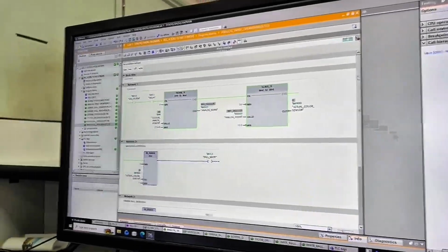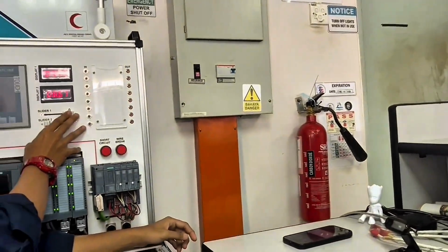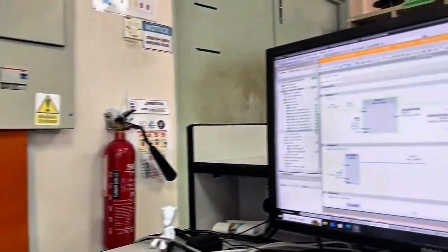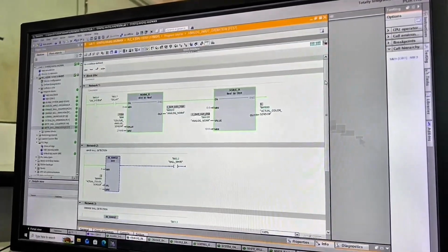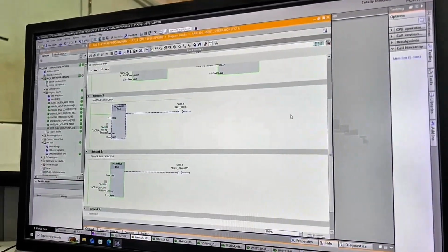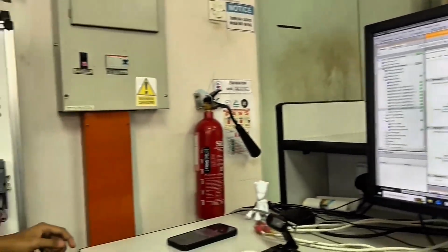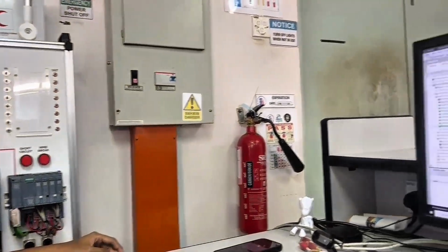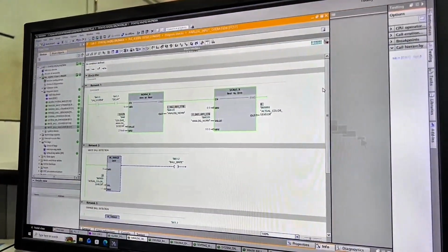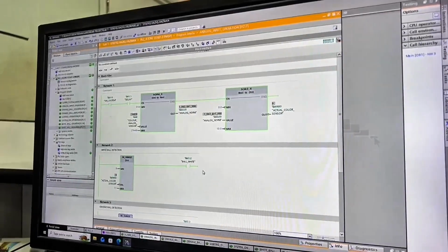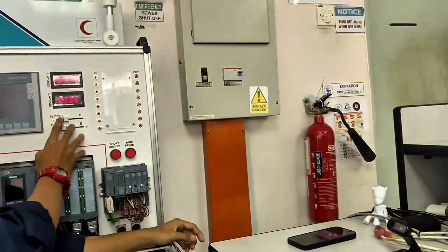For the analog input operation in network 1, after the system is turned on, the system will wait for timer T000 from the sorting operation network 3 to be activated. Next, the slider should be moved slowly to trigger the analog ball sensor, which will open the contact for the white ball. In network 3, the process is similar.